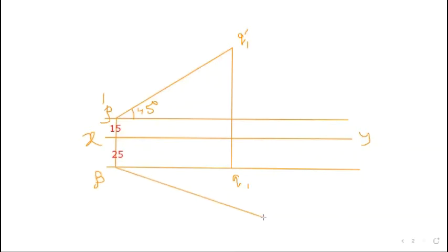And we measure by compass 60 millimeter. Suppose this is Q2. So this is the point Q2. So draw a line PQ 30 degree and measure by compass. So this is the 60 millimeter. Okay. Now from Q2, its front view will be a line. So from Q2, we draw a vertical line up to P dash, this line. So this will be the P dash Q2 dash.